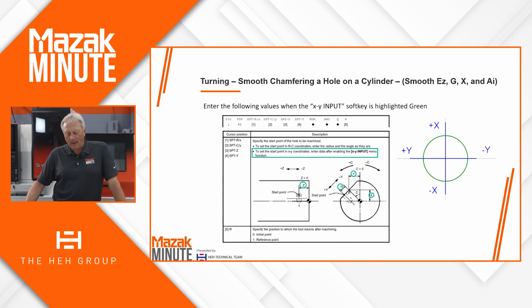If we look at the diagram on the left, you're going to see the small x and the small y. That is establishing the position of the degree that the C-axis will rotate. If you think about it, basically that's going to be your Pythagorean theorem. X squared plus y squared is going to give you C squared.